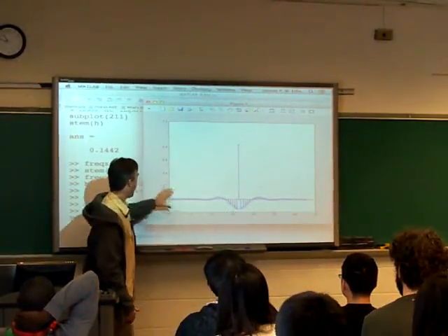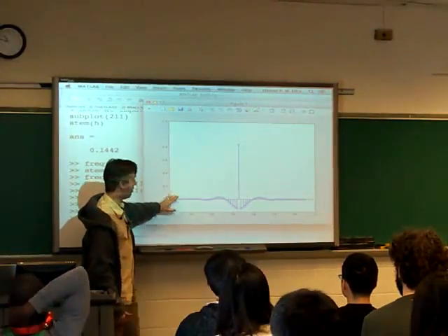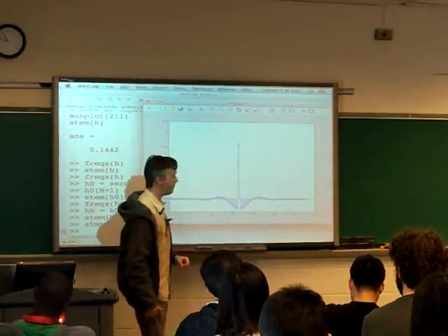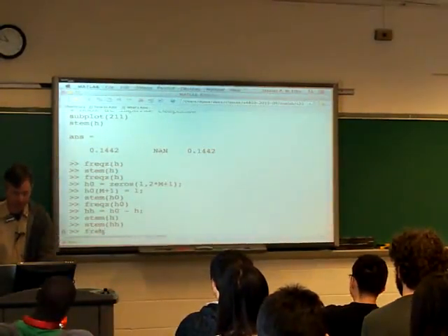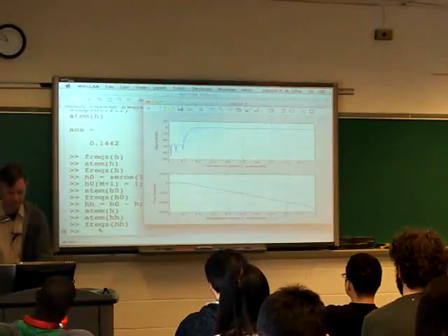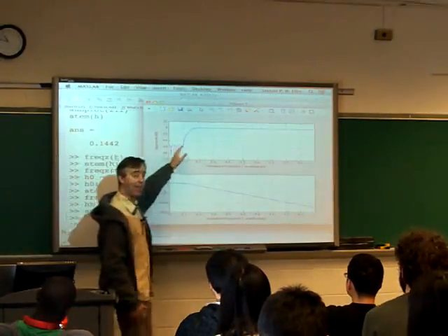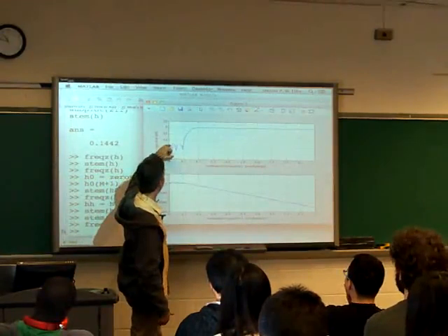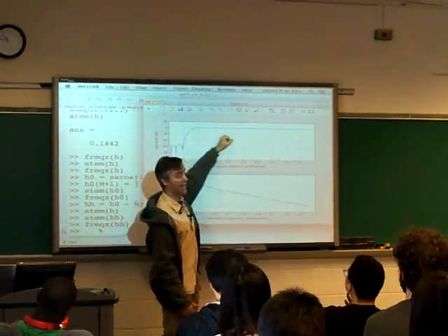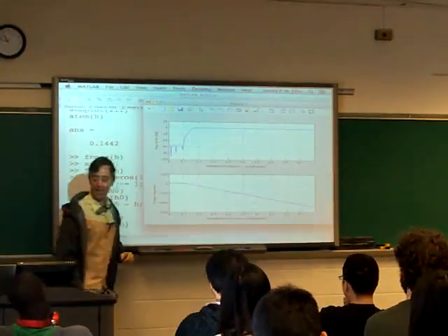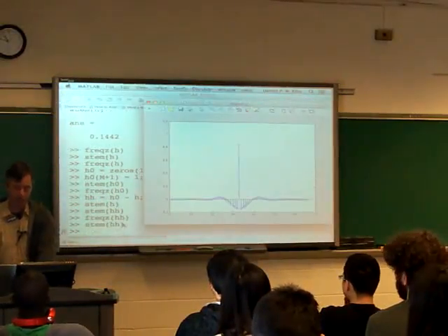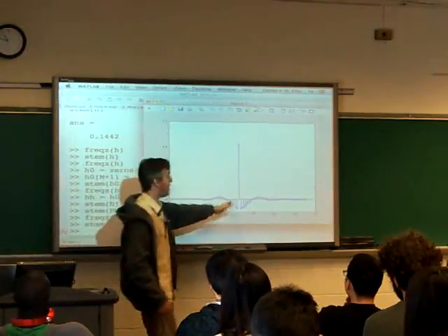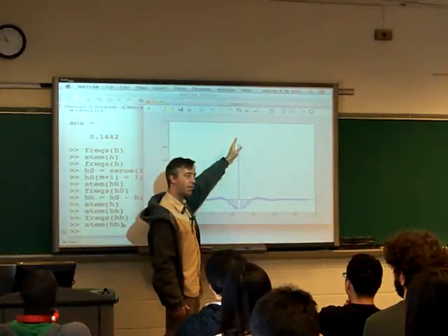This windowed thing only had an amplitude of like less than 0.2, so this thing sticks out in the middle. But that's all it is. And now if I look at the frequency of this, it's this very nice high-pass filter, again with -50 dB ripples and then a nice flat gain of 1 for high frequencies. And in a way, you can sort of view this as like, well, of course it's got lots of high frequencies, it's got massive discontinuity, it's got this spike in the middle.